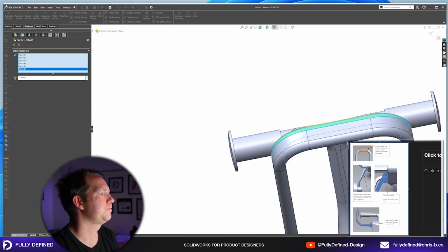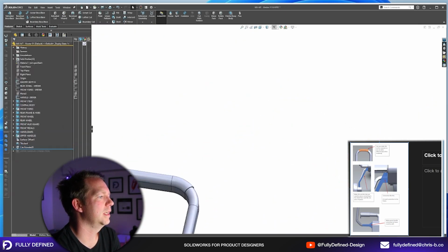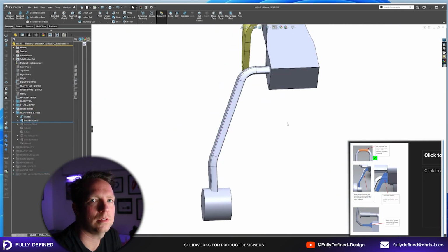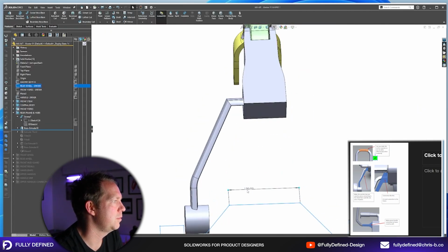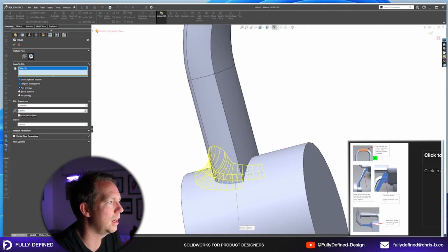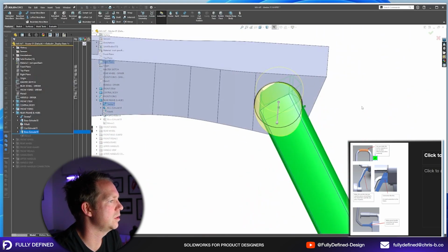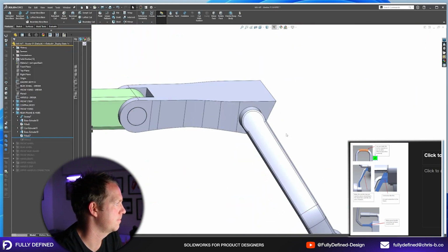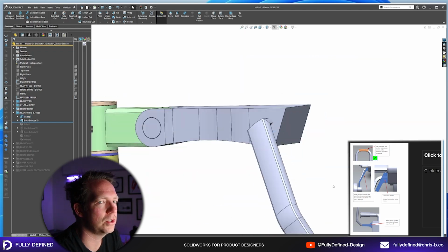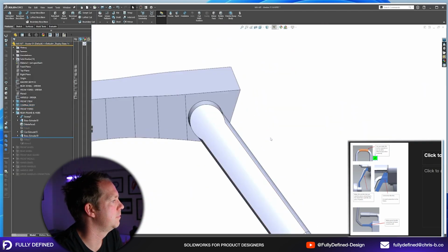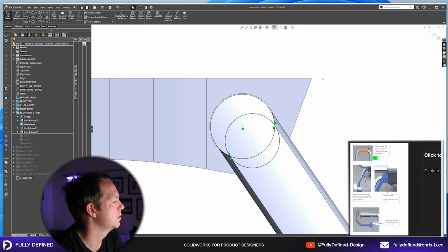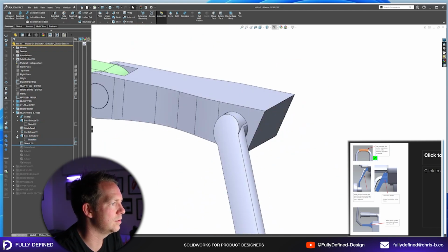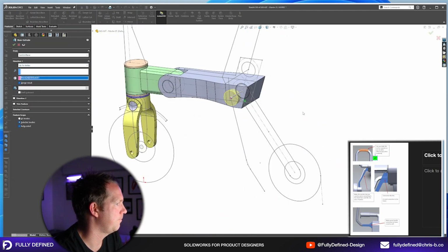Right, so with the handles, that's actually something that I was very comfortable with given our previous experience working together with this client. We've done a lot of strollers, baby strollers, prams, and a lot of them use aluminium extrusions for the legs, for the handlebars. So it's usually a profile that's extruded and then welded to other parts. And a lot of these products are manufactured in China, so very good. They really manage quality of these welds and finishings of these aluminium parts.